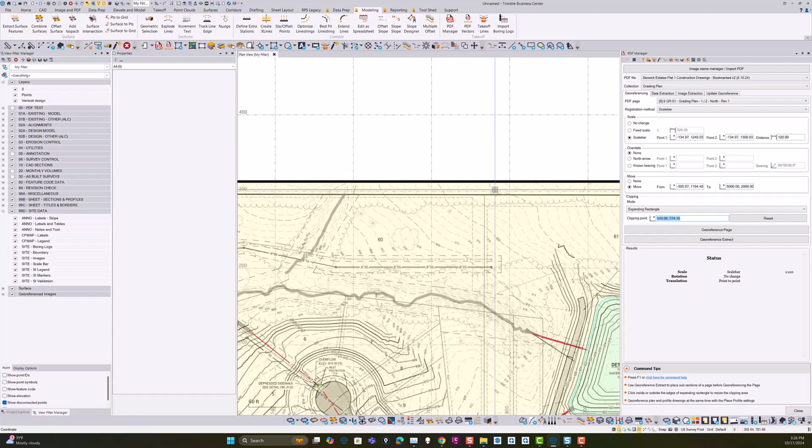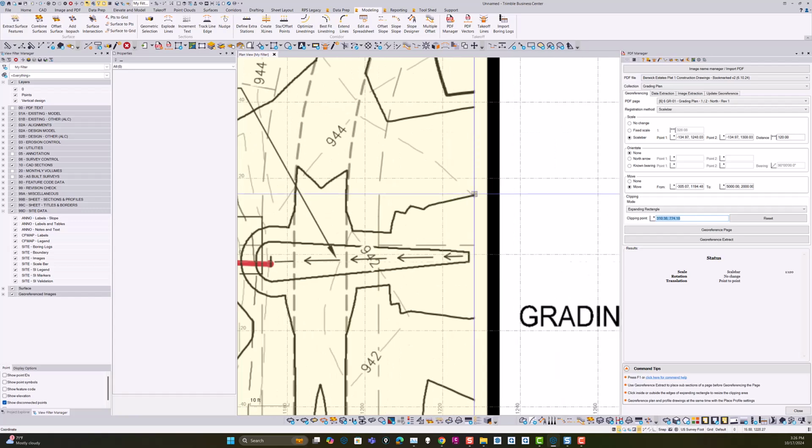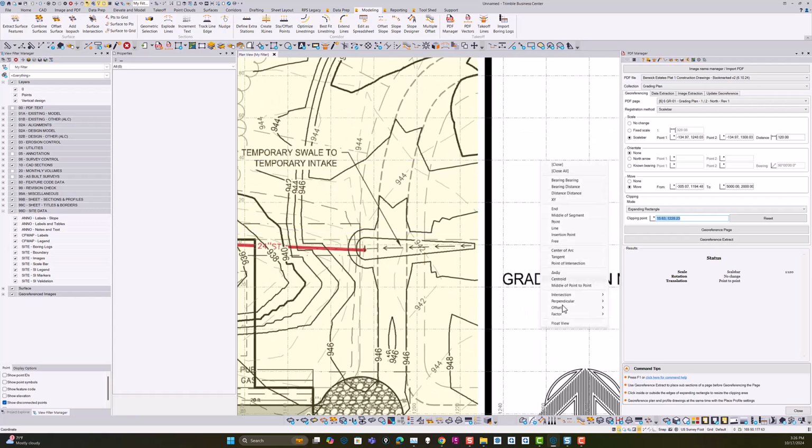And you can see we're doing vector snapping directly in here, and when we're actually positioning, we don't only get vector snapping, but you can use some of the right-click COGO snaps as well while you're working, and use 2 vector points, for instance middle of point to point, if you were doing an alignment.